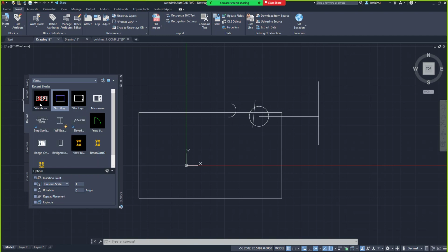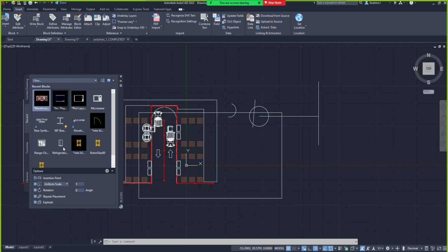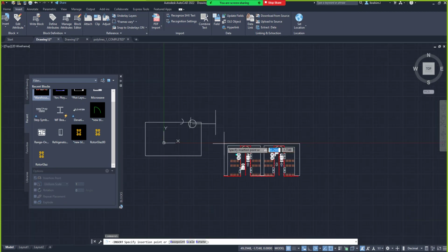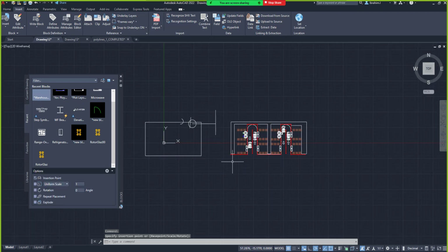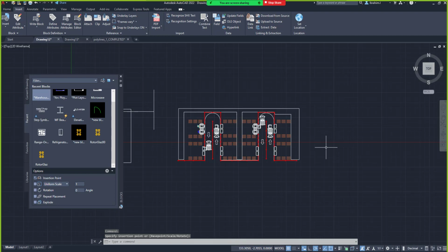And that railing was created using the create section. That means that railing is just project base, right? Which shows that this warehouse is global. If you want it on another project, you can always bring it in. If I want it here, all I need to do is select it and right click to select insert. It will ask me where do you want to place this guy, and then I can drop it on my workspace and I'm good to go. Are you with me? Yeah.